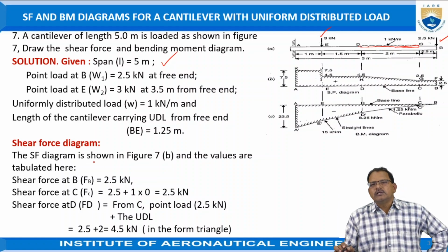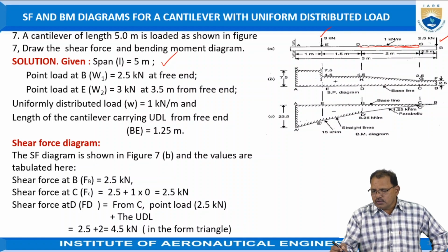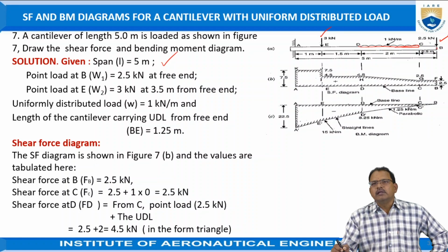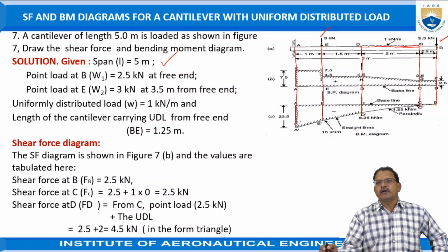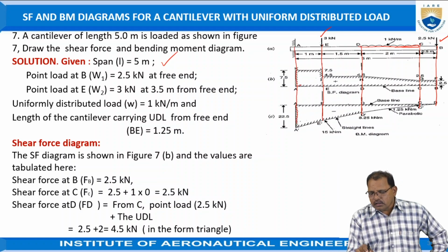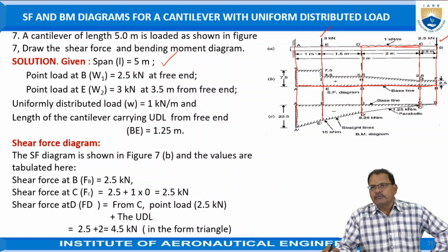So first of all, we have to draw the shear force diagram. So after drawing the cantilever beam and representing its forces which are acting on it, draw the vertical lines passing through the various points B, C, D, E, as well as A as shown in figure, and draw a horizontal line, which is representing the length of the beam as shown in figure now as the ordinate.